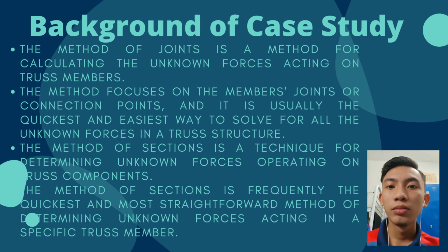The analysis should be identical to that of a single rigid body. Assume that each connection point between the members has a pin or some other amount of material. Any external reaction or load force that may be acting at the joint must be considered in your free body diagram. A normal force is applied to each of the two-force members connecting at that joint.